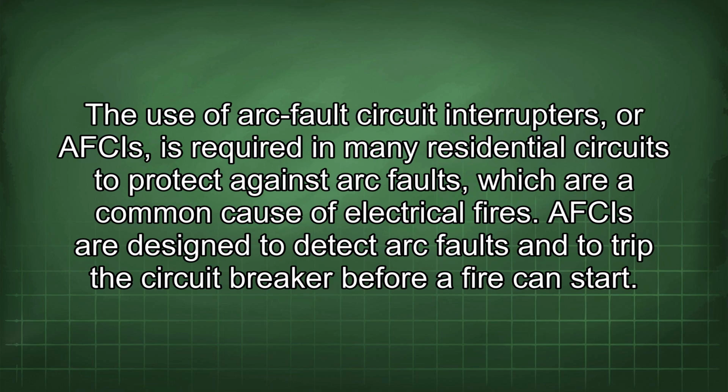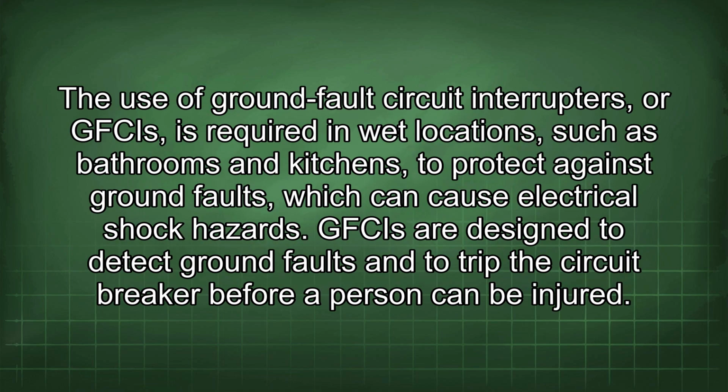AFCIs are designed to detect arc faults and to trip the circuit breaker before a fire can start. The use of ground fault circuit interrupters, or GFCIs, is required in wet locations, such as bathrooms and kitchens, to protect against ground faults, which can cause electrical shock hazards. GFCIs are designed to detect ground faults and to trip the circuit breaker before a person can be injured.